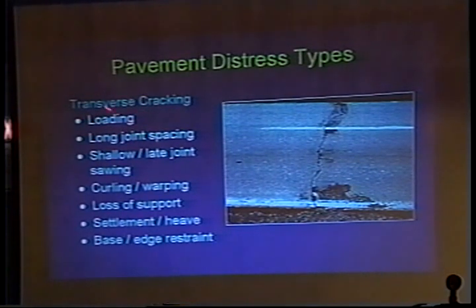Transverse cracks could also be caused by problems with overloading. Again, the long joint spacing that I talked about. Typically, they used anywhere from 40 to 60 foot back in the old interstate days. Now, for plain pavements, we're looking at 15.